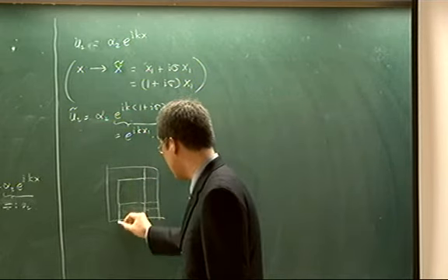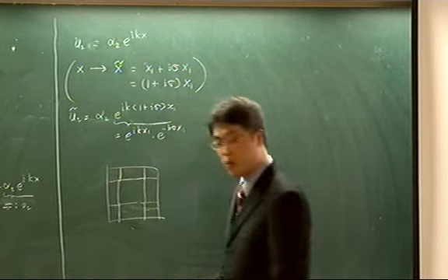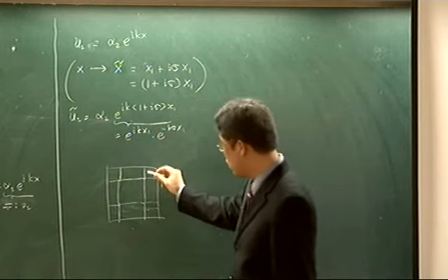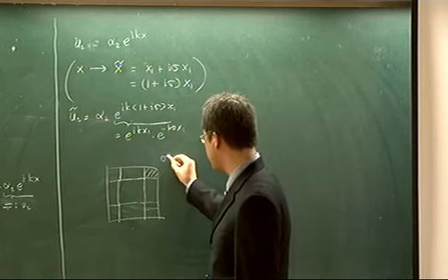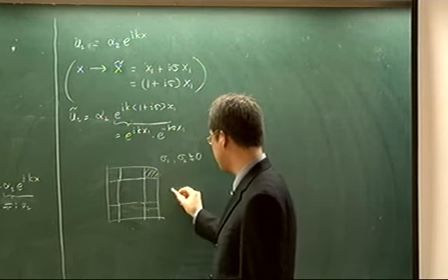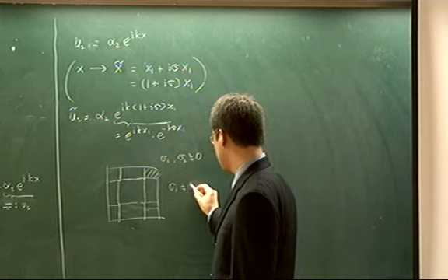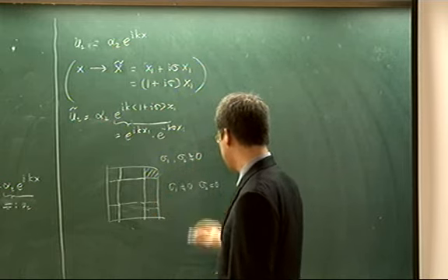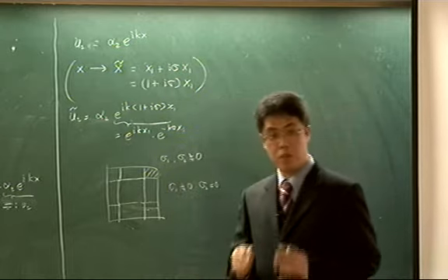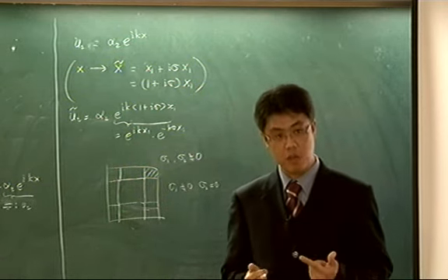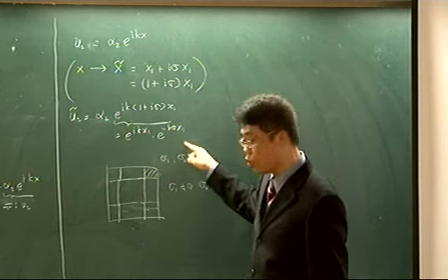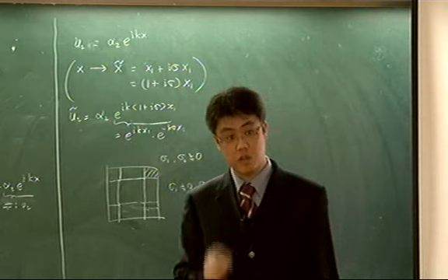You have here the corner regions, because you have x1 and x2 coordinates, and two coordinates meet in this area. That means in this area you have the damping parameter sigma 1, as for example sigma 2 is non-zero, but in this one sigma 1 is non-zero, but sigma 2 is 0. Just like this you can formulate, but in the end, outside of the PML layer you can put zero boundary conditions. You can put that, because sigma is very large, for example, then the solution of U2 on the boundary in the PML layer is very small.